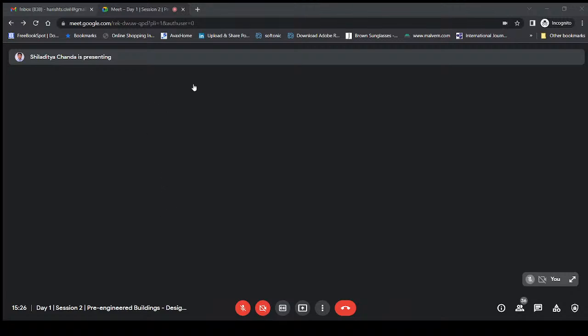Here is another insight. This is the eave strut. We talked about the eave strut, right? This is a normal bracing system. Now suppose you put this bracing as tension only, because these are bracings or cables, this cannot take compression. So there must be a member over here that takes care of the compression force.